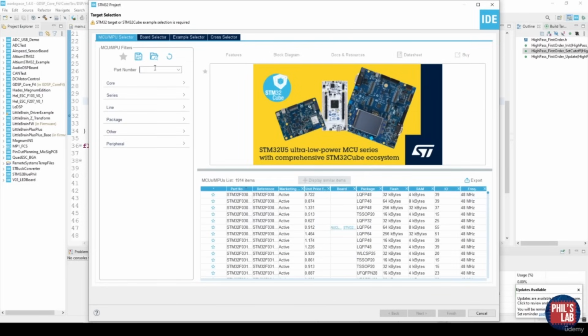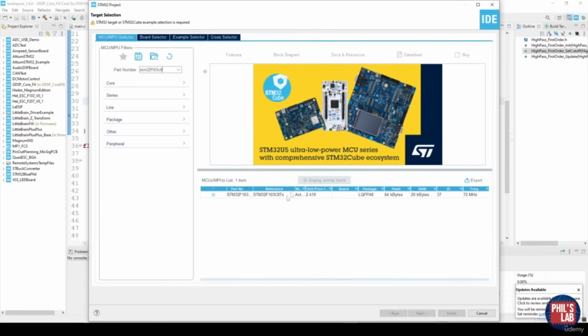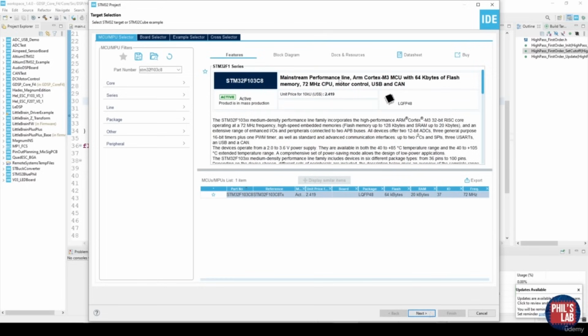All we have to do is type in our part number, which is the STM32 F103C8, and if we see here, it's the C8TX, and again, X is a placeholder. It shows us the package, size, the flash, and RAM, how many IOs we have, the maximum frequency we can run this device at. So click on that. It tells us a bit more about it, so you can see you can operate from this supply voltage, it has USB, various peripherals, and so forth. And this is actually a pretty useful tool to select which STM32 microcontroller you might want to use.